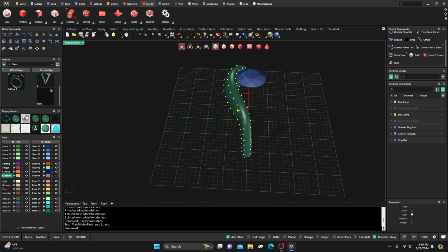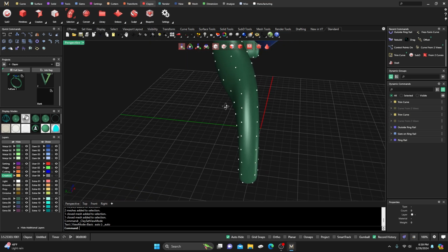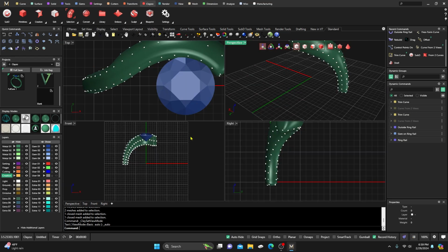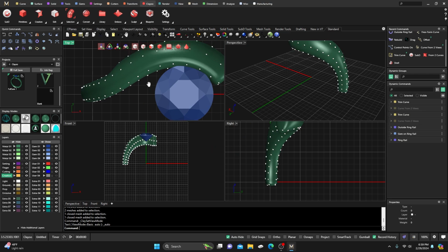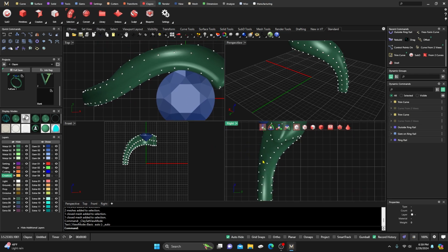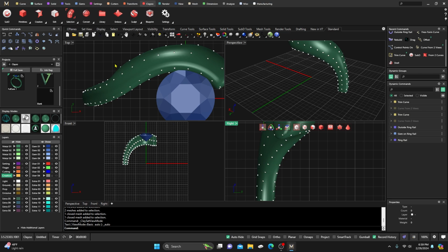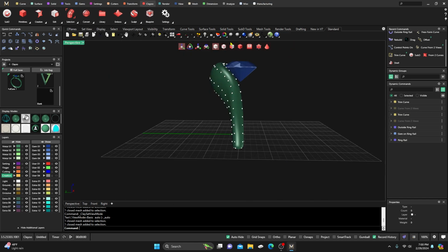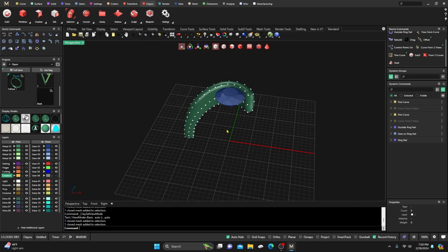So it gives us something like, if I go to shaded mode and go to smooth, we can see that it has a little bit thicker here and moves up to where it's thinner. We could probably go up even a little bit more. So let's go in here. Let's keep a look right in here. And we'll go up. Let's see, where are those? These here. Hold down Shift. These here. And let's bring those in a little. Give it a nice, smoother shape there. Yeah, but that's pretty much it.